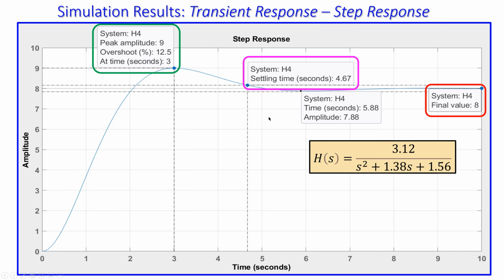The formula has some region where it is not exactly 4 over the absolute damping, but a little bit in between 3.9 and 4.7 for that 2% criterion. Most of the time, most books use 4, but it can of course be a little bit smaller. It can also be a little bit larger than what you have estimated or calculated.